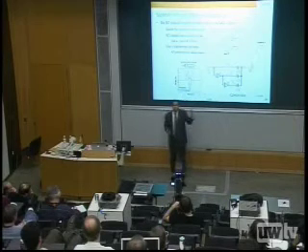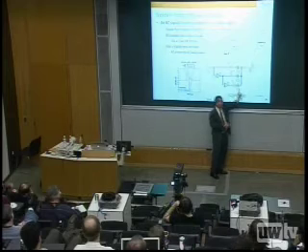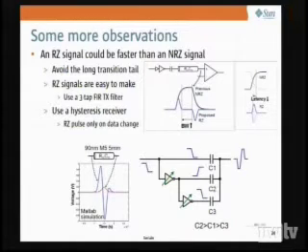So I can sum voltages by simply adding together the outputs of the capacitors. So this gives me a chance to make a very inexpensive N-tap FIR filter. Here's a 3-tap filter that says that for a falling edge here, I could have a falling edge, a rising edge with perhaps twice the tap weight, twice the capacitance, and then another falling edge, which gives me that sort of two-mode pulse on the output of the wire.